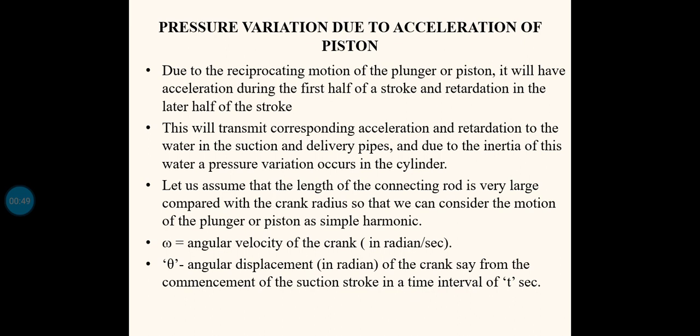That means during the suction stroke, when the crank rotates from 0 degree to 90 degree, the piston will be moving with acceleration. From 90 degree to 180 degree, the piston will have deceleration. Same thing in the next half also, that is from 180 degree to half of the 360 degree we will have accelerative motion. From there to 360 degree we will have deceleration. So this acceleration and deceleration of the piston will have the same effect on the fluid flowing through the suction pipe as well as the delivery pipe.